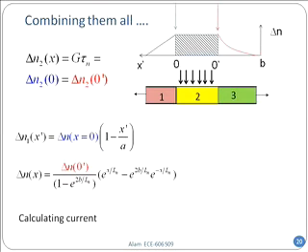Okay, now do you see it looks like some sort of bridge in the middle, but look, this is the carrier concentration. In the middle, uniform light shining. So what is the value of delta n in the middle section? G multiplied by tau sub n, right? At a certain rate it is being created and it's recombining at the same rate. And so steady state is G tau sub n. And on the left hand side, trap free going to the metal contact, it is going linearly to 0. So that's one side. The other side is full of traps, and therefore it is disappearing faster, and therefore before getting to the contact.